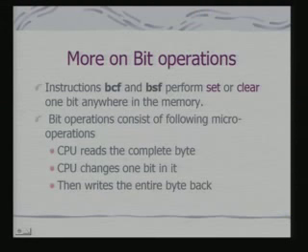So, the instructions we have seen, BCF and BSF, perform set or clear of one bit anywhere in memory, and bit operations consist of the following micro operations. The CPU reads the complete byte, the CPU changes one bit in it and then writes the entire byte back.